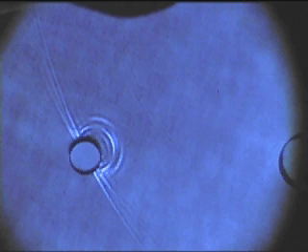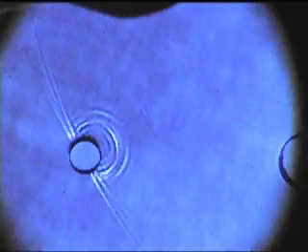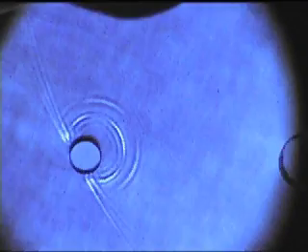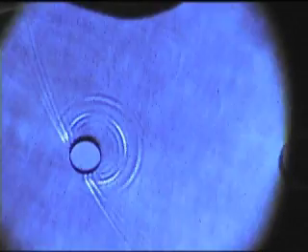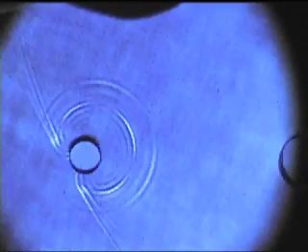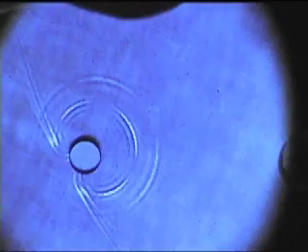This angle increases until the wavefront is at the halfway point of the hole. Here, a glancing incidence occurs. The reflected transverse wave that forms as a result of this interaction takes on the cylindrical shape of the hole as it propagates away from the reflecting surface. But at any angle away from the perpendicular, an incident shear wave at a solid to free boundary interface will mode convert, and, in addition to the reflected shear wave, a reflected compression wave occurs. The compression wave moves off in a similar cylindrical shape, but at about twice the shear velocity.